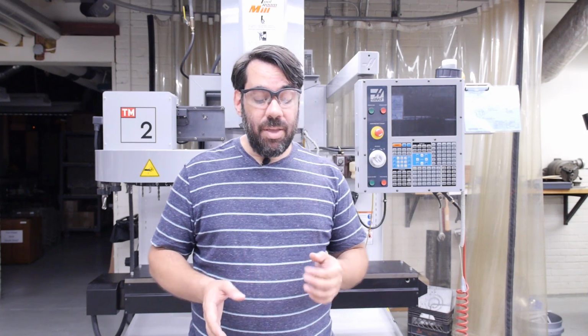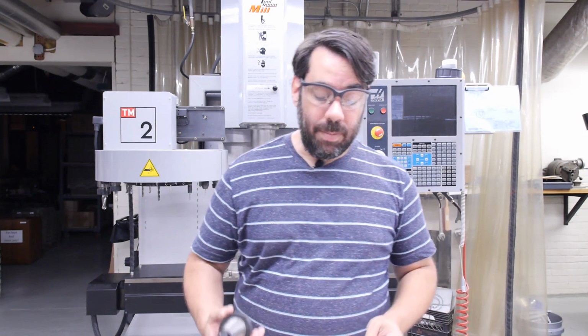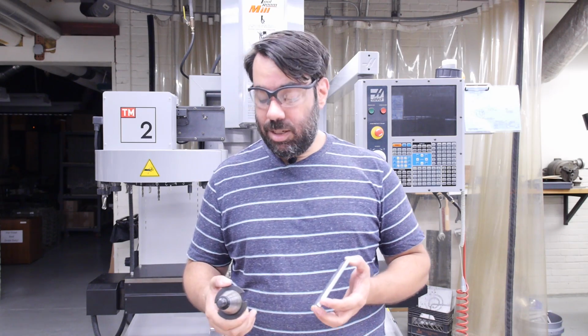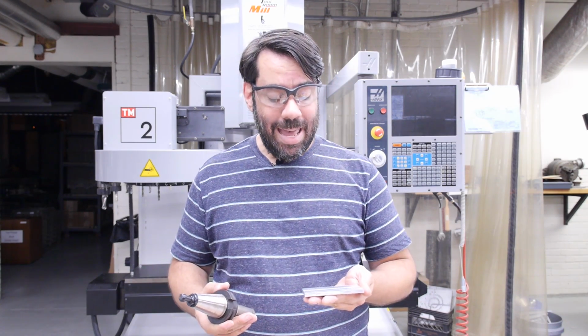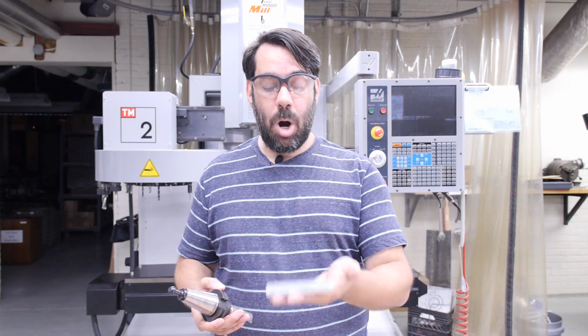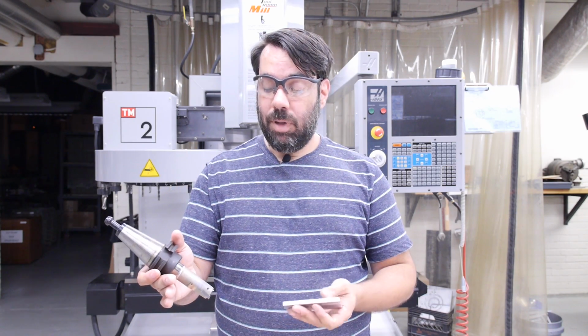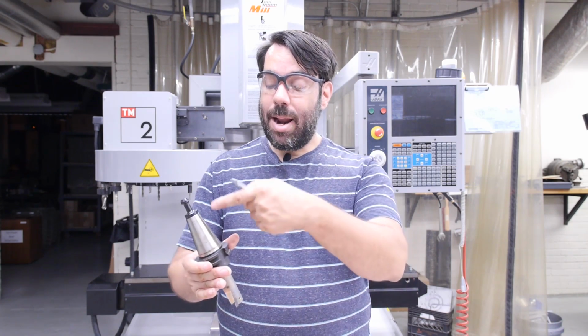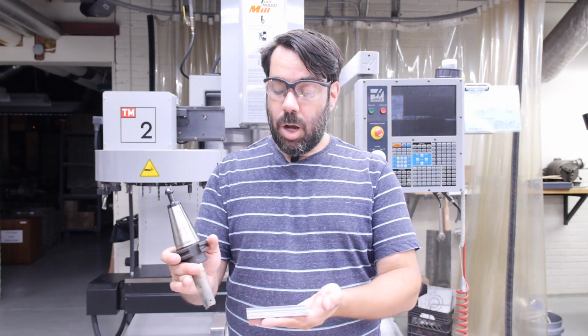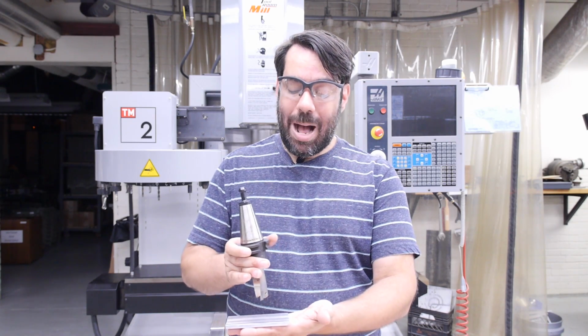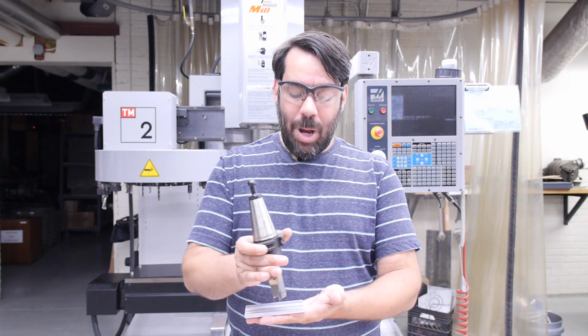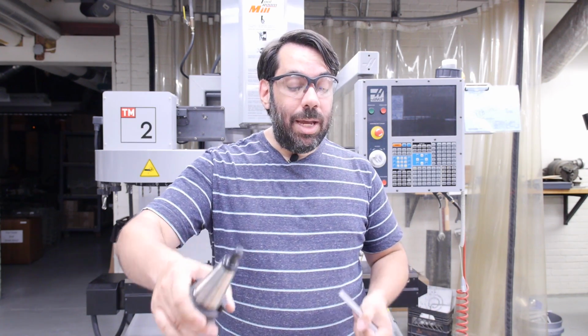Starting with the advantages, the first one is the ability of a CNC machine to command multiple axes of simultaneous motion. The easiest way to explain this to the students is to take a workpiece and pick up an example cutting tool. Of course, be careful of the cutting end and try not to touch the precision machine taper as well. So pick up the tool and tell the students, when they learned how to use the milling machines, for example, we taught them they could move the x-axis or the y-axis. However, if they tried to move both the x and y-axis, they couldn't do so very accurately because they're essentially using the machine like an old school Etch-a-Sketch.